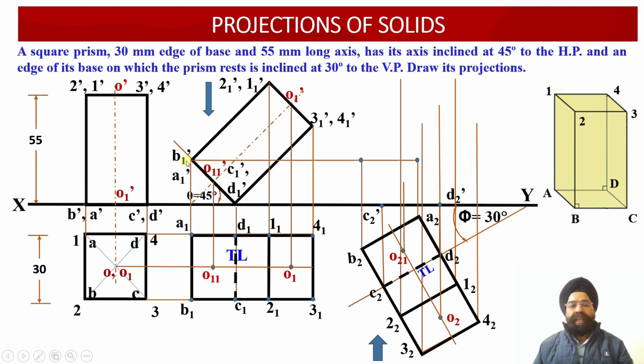Next, we have got another 2 points corresponding to the base, B1 dash and A1 dash. So now we have drawn a horizontal projector line through B1 dash and A1 dash. So wherever this horizontal construction line or projection line intersects with the vertical projector lines drawn through the points A2 and B2 of the plan projection view, we will be obtaining the points A2 dash and B2 dash.